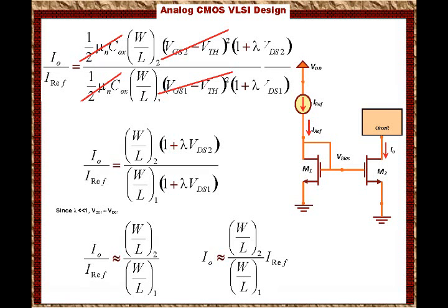And that's the beauty of the circuit. Basically, I will be able to design the W over L ratio of the transistor, so the geometric structure, the size of the transistor, determines how much current will go through that biasing circuit, determines the current of the current source. And this is very powerful.